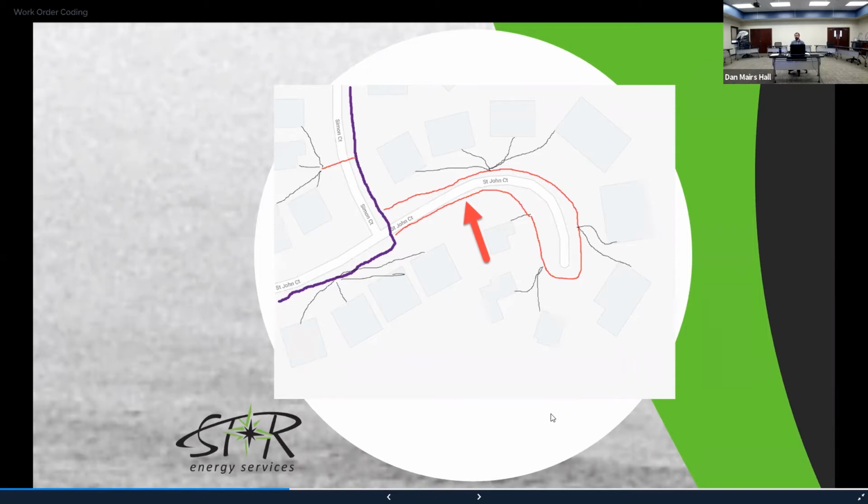If you do come to a point where, well, why don't we just make this a loop fed cul-de-sac in the first place, I would recommend either talking to your GFR or your engineer about what you should do and how you should code that, because technically it is a tie line. It's tying basically from the same point at the beginning and the end, but you now have two available ways that you could feed this. So just check on that with your GFR, but typically they don't look too closely at the 100 codes, but if you did get audited, they might ask you about this.